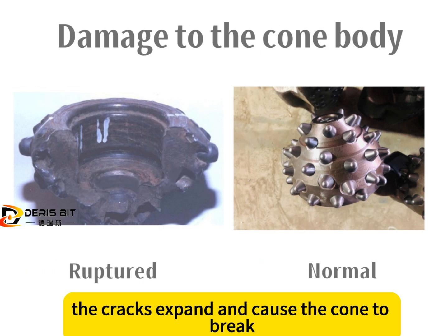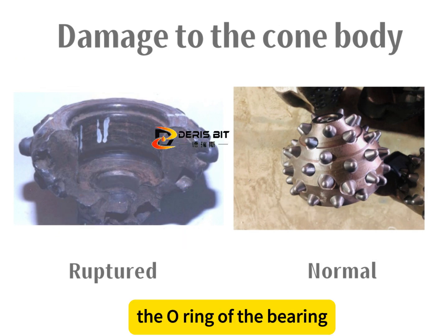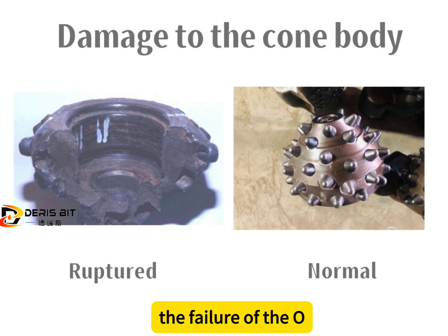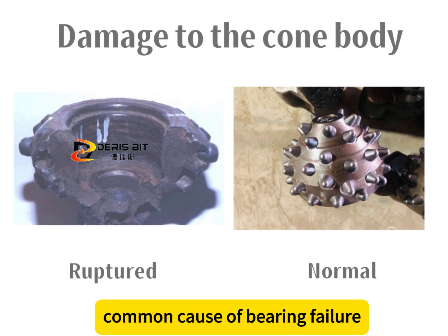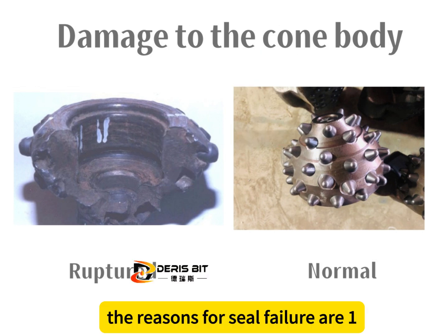3. Hydrogen sulfide corrosion in the well leads to hydrogen embrittlement. 4. Improper heat treatment causes microcracks in the cone housing. When the drill bit is working, due to fatigue impact load, the cracks expand and cause the cone to break.